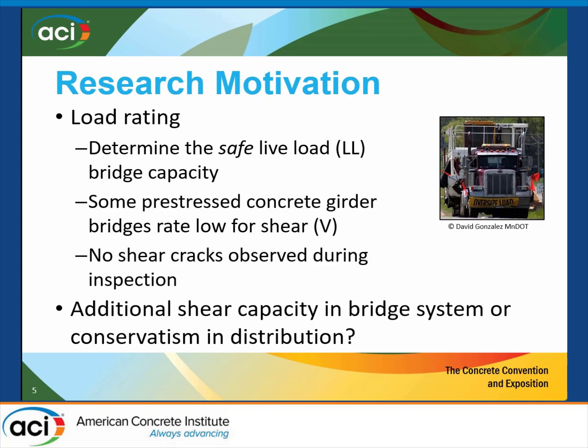So with that in mind, I'll go a little bit into the motivation here. This side of the project really was looking at load rating. If a structure exists, the goal is to find out the safe live load carrying capacity of that bridge. So how much weight, how much truck traffic can go across. Where I'm from, some prestressed concrete girders rate low for shear, meaning if you run the numbers in an equation, the final value says your bridge isn't performing as it's supposed to.